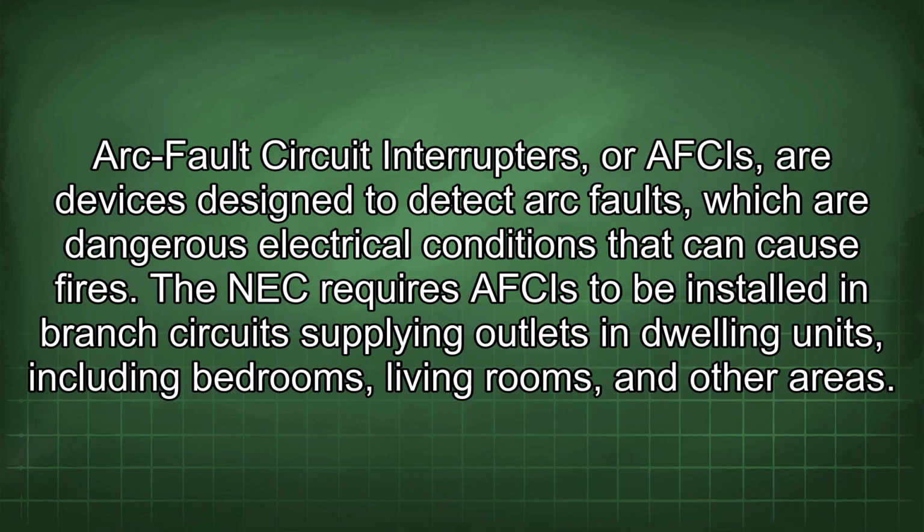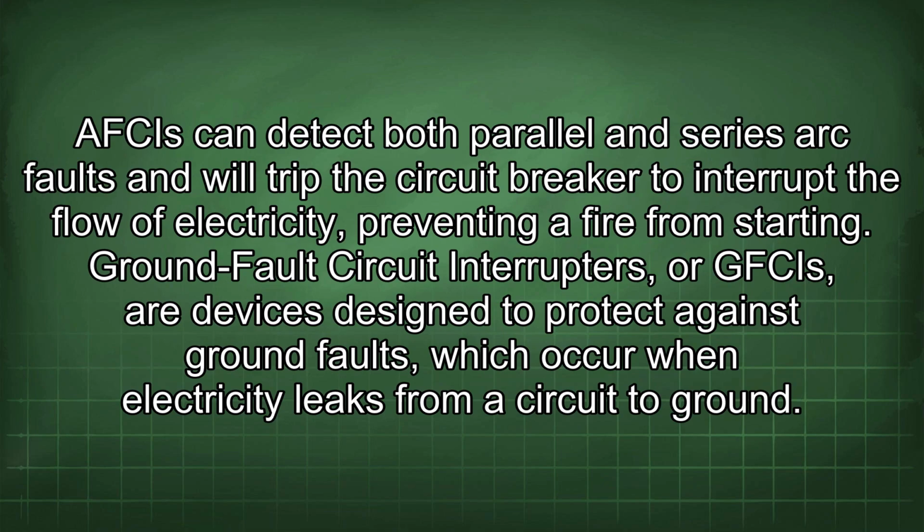Arc fault circuit interrupters, or AFCIs, are devices designed to detect arc faults, which are dangerous electrical conditions that can cause fires. The NEC requires AFCIs to be installed in branch circuits supplying outlets in dwelling units, including bedrooms, living rooms, and other areas. AFCIs can detect both parallel and series arc faults and will trip the circuit breaker to interrupt the flow of electricity, preventing a fire from starting.